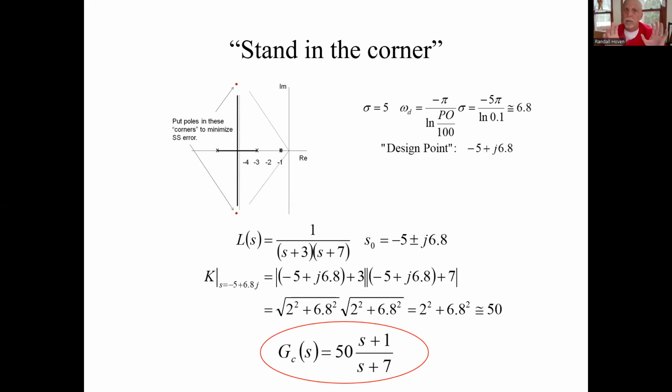By those specs, putting the poles in the complex plane this way was based on the dominant pole concept. That's why we might not meet specs exactly, because remember, additional poles and additional zeros affect what actually goes on. So those were based on an ideal prototype second order system, but we don't have that. So we're using it as a guideline. That's why we do MATLAB after we do this sort of analytical work.